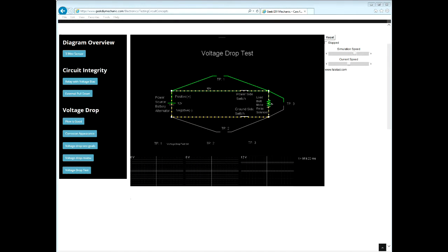On the other hand, test point 3 is across the load, creating a voltage potential difference. In this case, the scope reads 12 volts. This means that this load consumed all of the 12 volts, which is what we would expect due to Kirchhoff's voltage law. Nothing else is robbing any current or voltage. This is what we expect as the result of the voltage drop test on a healthy circuit.